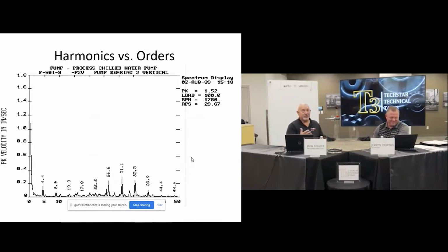But yeah, if you look at the quality of the spectrum, at the time we talk about lines of resolution, which gives you better looking spectrums. I think we were only able to go to like 800 lines at the time. That was a Cadillac at that time. Now you can go out to 10,800, I think, lines of resolution. And keep in mind, the more lines of resolution, the longer it's going to take to collect that data too. It makes sense.